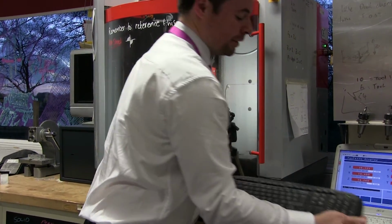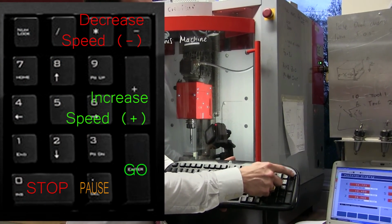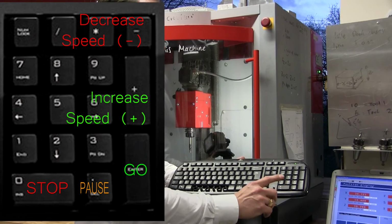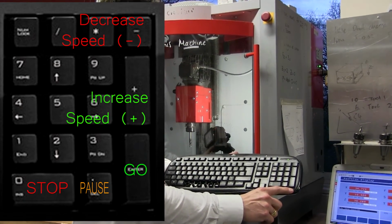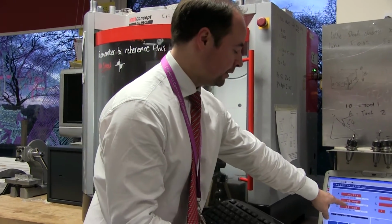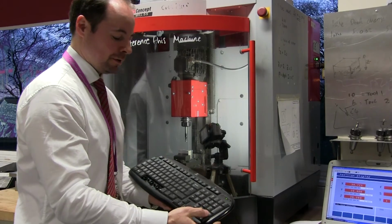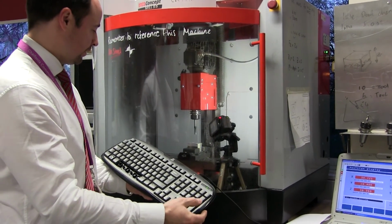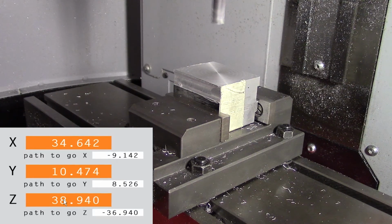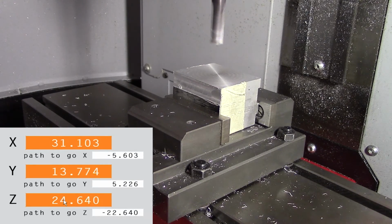Now before you hit go, so this is go, this is stop, this is pause, this is faster, this is slower in terms of feed rate. So if you hit pause, hit enter twice to get it going again. Now I'm going to hit go, and I'm going to check the Z value and check that that value is the distance from the bottom of the cutter to the top of the work. So it should slow down when the Z value gets to 2 mil.